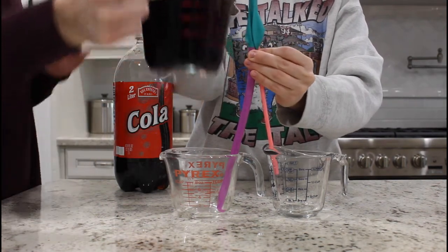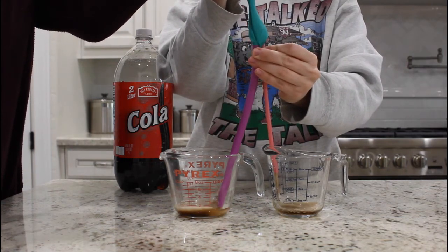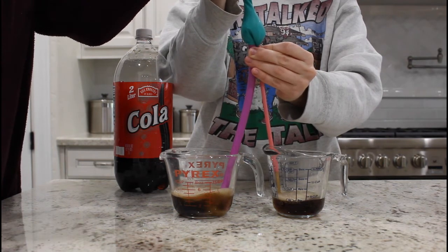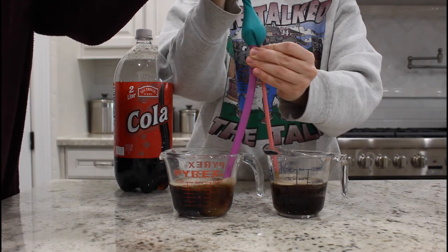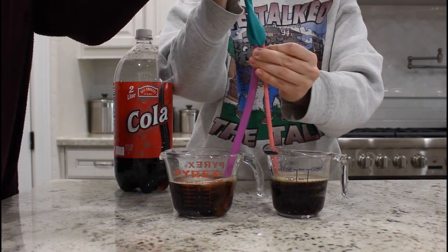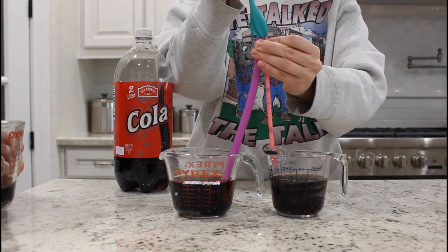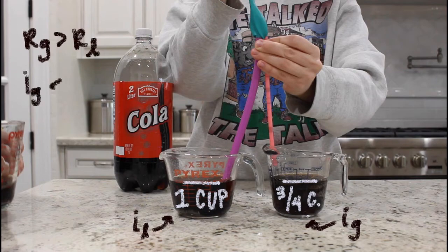And if we think about it as two different straws, we would think that whenever it splits, if we have a bigger straw, which is Rl, then we're going to have more current flowing through there because it's less restricted. So a greater fraction of the total current is going to flow through Rl compared to Rg. But it's going to be a fraction of the total current because the current that's going into one node at one end of these two resistors is going to have to come out at the other end.